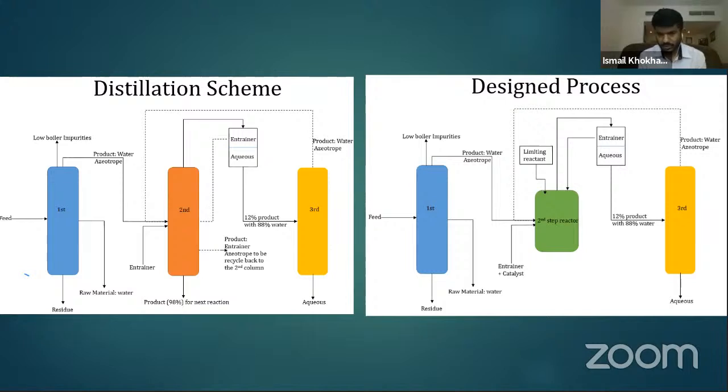As I told you, as a process engineer it's not just about taking out samples, but removing samples properly during kinetics or during the generation of the VLE curve is very important. Make sure that you have a proper sample, because if you don't do proper sampling, there is contamination. You are not going to get proper results. And if you don't have proper results, don't expect proper designing of equipment for yourself.